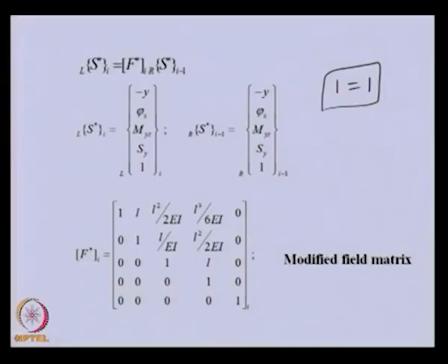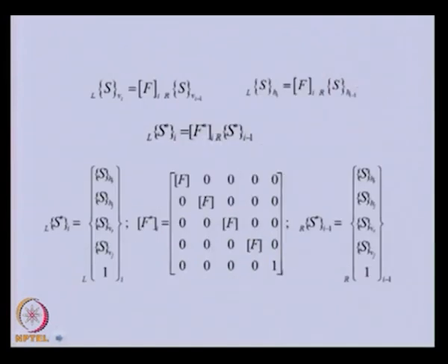So for that case, when we are considering both plane motions and also want to consider the damping or gyroscopic aspect, then here you can see this is the state vector: these two are in the horizontal plane, and these two are in the vertical plane. In the horizontal plane itself we have taken the real component and the imaginary component.